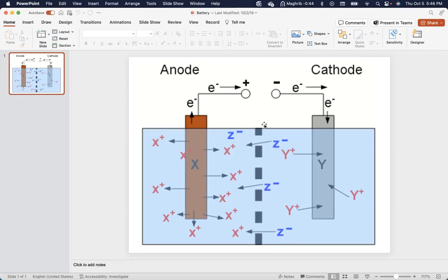And we saw this in the lab. If we run a current through our D batteries, the potential difference, what we call the terminal voltage, decreases as I run current through the system. We'll talk more about that next chapter, but basically it has to do with resistance, or what we call the internal resistance, as you saw in lab.